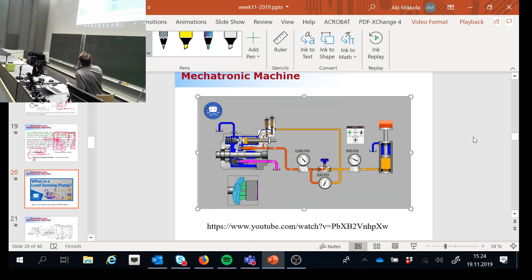The cylinder just kept moving nice and steady, and our pump found out that it needed to increase the outlet pressure setting automatically. So what we found out is we can have a pump that is set at a pressure that's just a little higher than what's needed at the load, instead of being always at the pressure cutoff pressure, which could be considerably higher. And because we know we want steady speeds to our hydraulic cylinder, we don't wish to see any fluctuation in speed. Every time we take a brick off the stack, or every time we add a brick to the stack, the pump knows to adjust itself accordingly so that the flow rate through the needle valve doesn't change. That's the nature of a load sense system, and that's a brief introduction to load sense pumps.